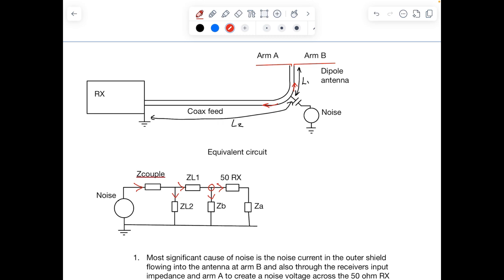They're relatively free to radiate, and they do radiate. And of course, the proper dipole antenna is likely to pick these up, and that's another mechanism where noise is coupled into your receiver. It gets re-radiated by the outer surface of the coax and picked up by the dipole antenna.